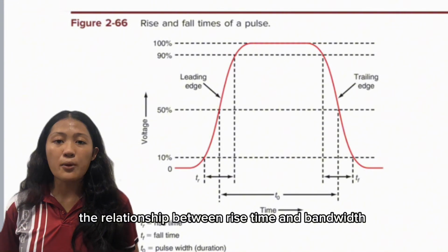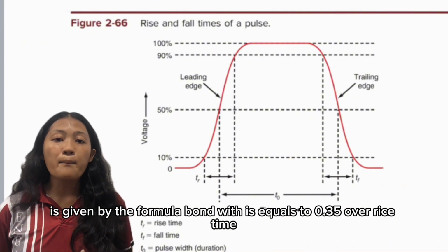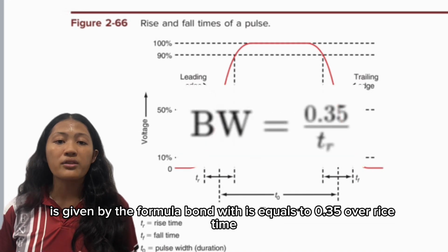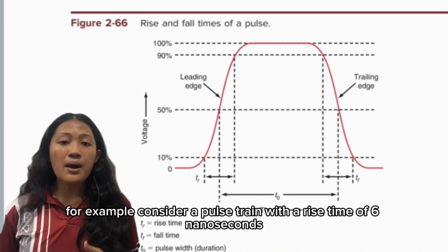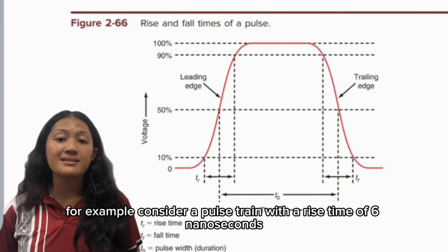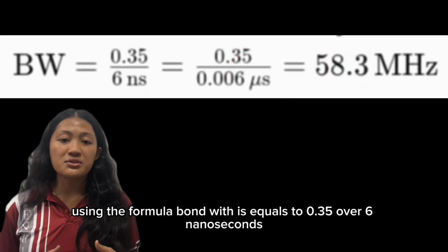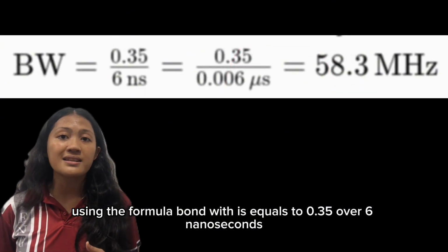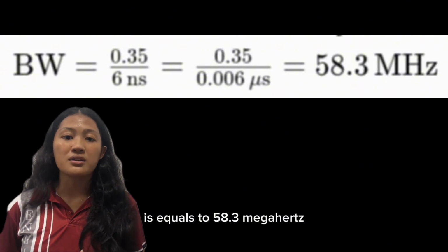The relationship between rise time and bandwidth is given by the formula: bandwidth equals 0.35 over rise time. For example, consider a pulse train with a rise time of 6 nanoseconds. Using the formula, bandwidth equals 0.35 over 6 nanoseconds, which is 58.3 megahertz.